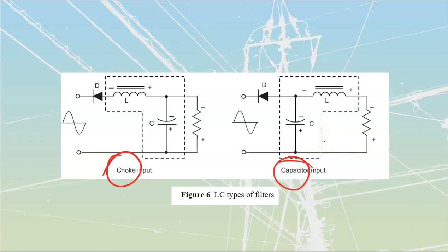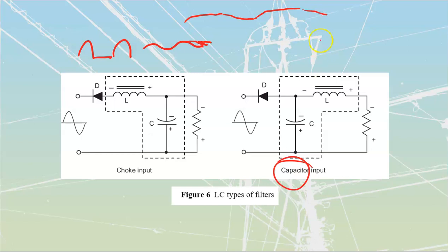And then they can aid each other. So this one over here, you've got to remember that if I've got that rectified waveform, this is now going to change it into this gentler type of waveform over here. This is then going to charge up to those peaks, and it's going to discharge. So it's going to start extending those peaks so that we get a much better regulated voltage. So it ends up being more like a flat top, and then it sags out, and then it comes into a flat top, and then sags out, etc. That's what we get out of our choke input.